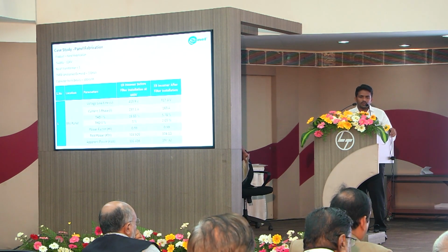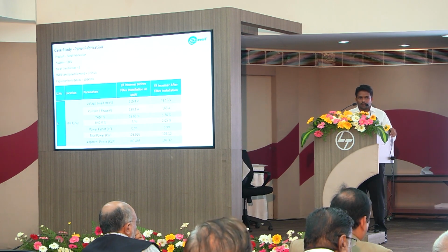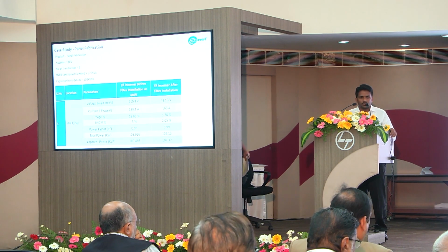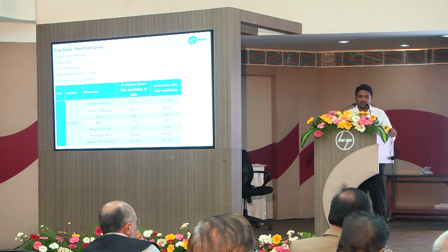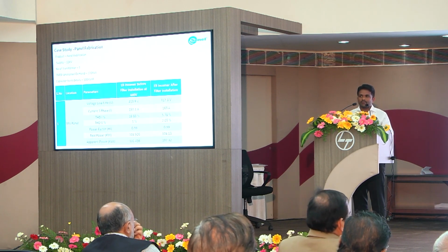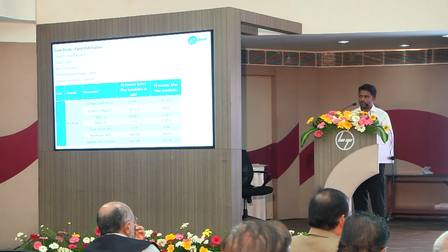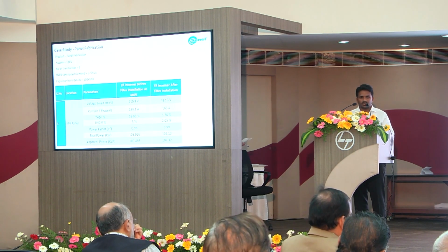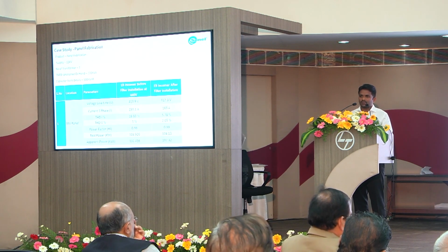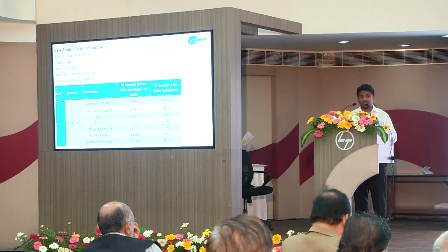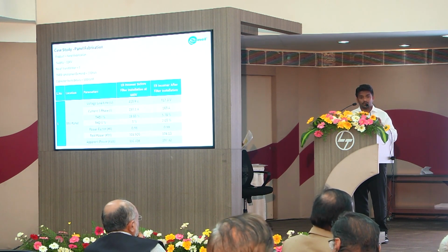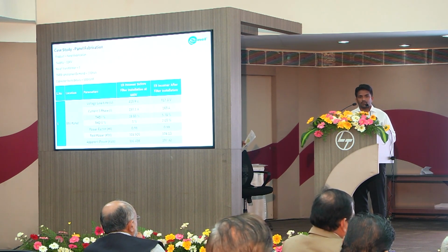Then an example of panel fabrication. On an easier note, I don't want to present it as a thumb rule for how to do a power quality analysis. What I personally understood from this exercise was, when a single-phase load is the predominant load inside the customer premises, our approach was towards triplen harmonics. When we had a processing load, for example a textile plant or other three-phase loads, we were focusing on the 5th and 7th order harmonics.